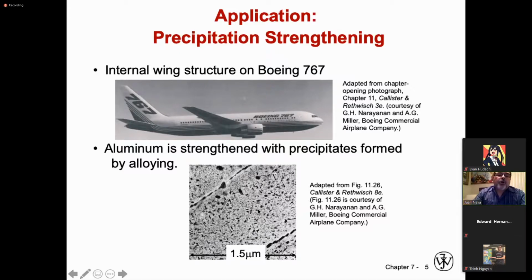So, for example, in aluminum alloys, it is very practical to strengthen the alloy. This is a grain boundary. That's another grain boundary. By promoting the precipitation of second phases within the grain, each one of these is a precipitate that is forced to be formed inside the grain. So when the dislocations move, you will need to apply more energy in order to promote any deformation. So you are making the material stronger. Remember, strengthening is all about creating impediment to the movement of the dislocations.